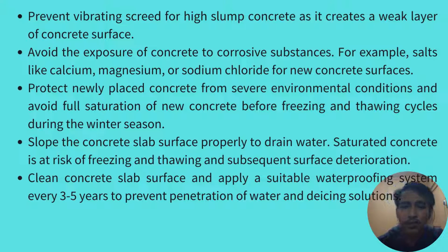Slope the concrete slab surface properly to drain water. Then saturated concrete is at risk of freezing and thawing and subsequent surface deterioration. And then clean the concrete slab surface and apply a suitable waterproofing system every 3 to 5 years to prevent penetration of water and deicing solution.